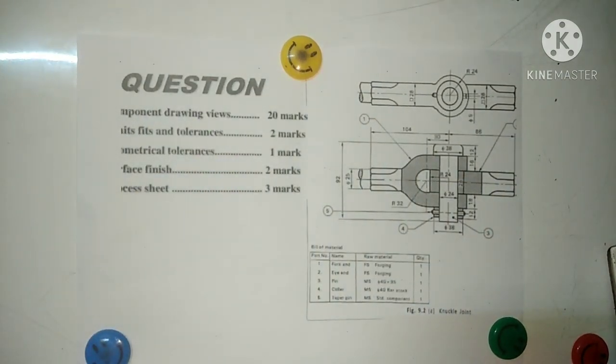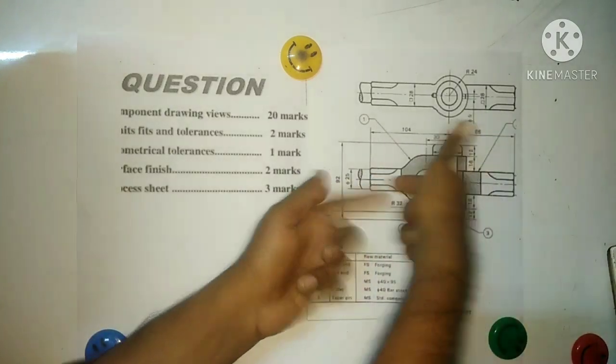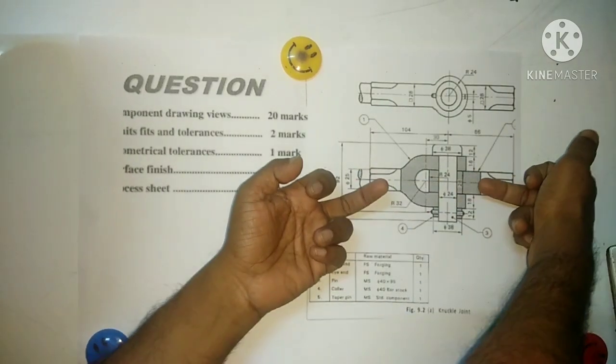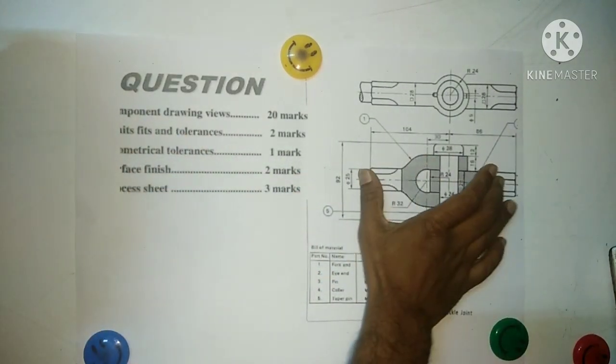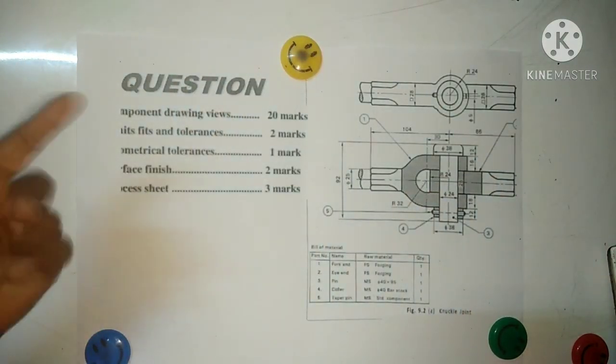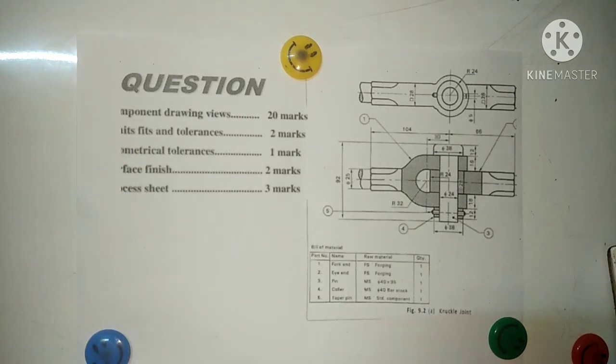So for that purpose we are using this knuckle joint. It is also used as a joint between the links of a suspension bridge, and in the steering system, in between the steering rod and pinion of steering gears. The knuckle joint is used to connect two rods under tensile load. That's very, very important. One connects to the tractor, one connects to the trailer, so it is like a tensile load. Wherever you are going to have tensile load, there you use a knuckle joint.